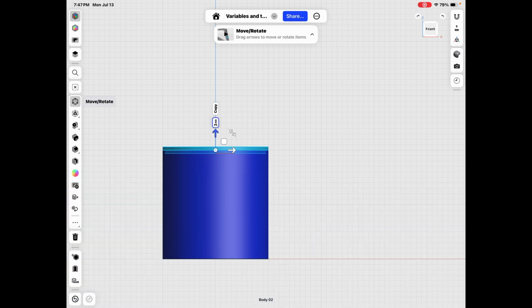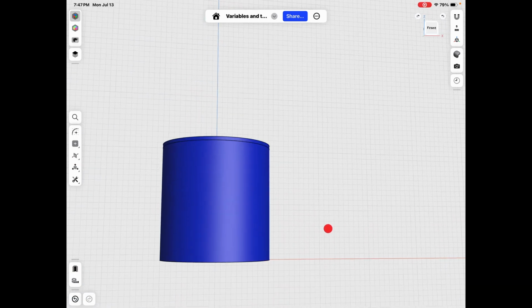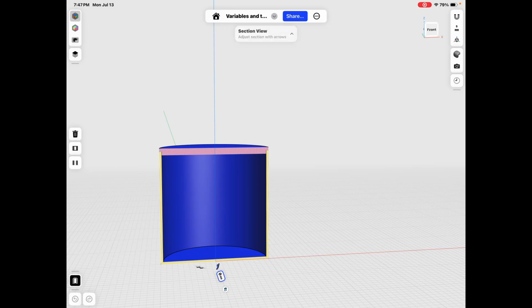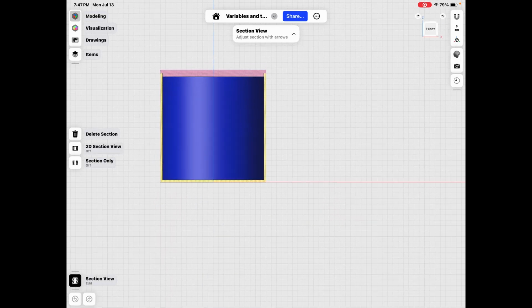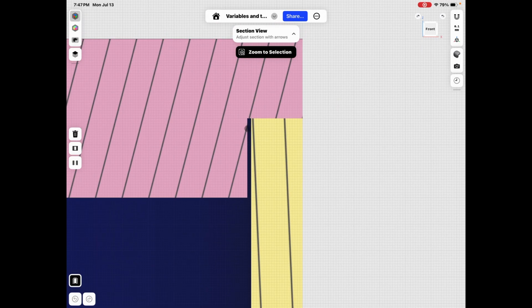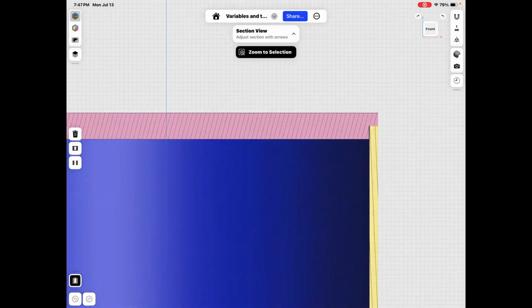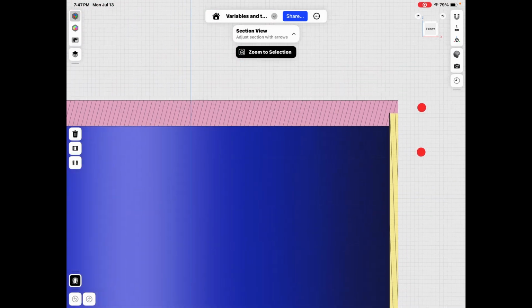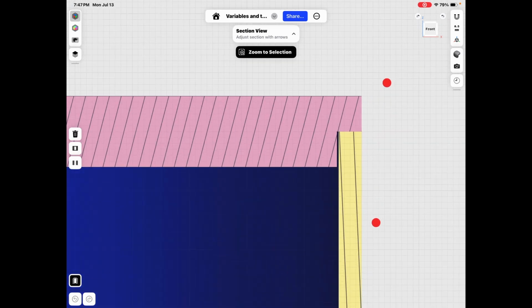All right. So there's the lid. But what the offset did, let's see what this is. And I'm using the section view, right, where we're slicing it. We can see that slippy is not going to be exactly perfect. But what happens is we know that it's going to grow 0.15 when we print it, and it's going to be a pretty good fit at that point.